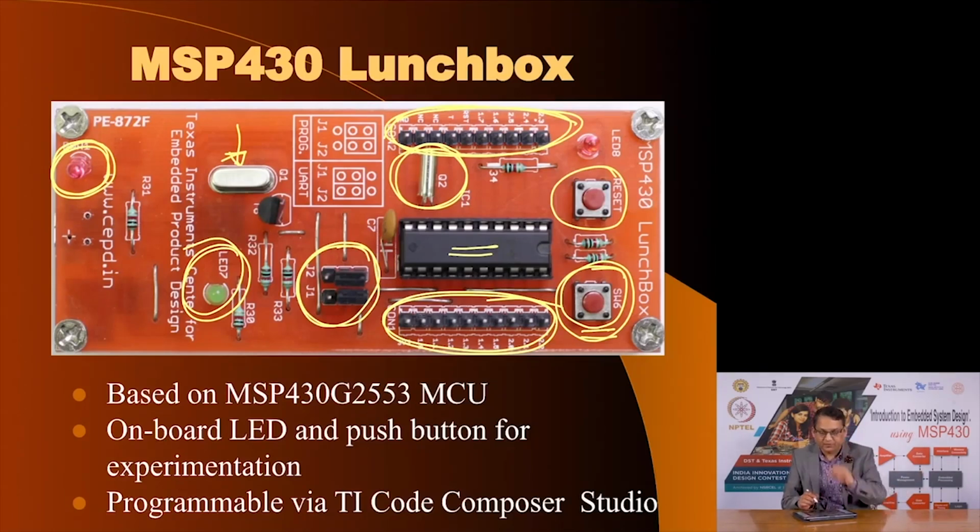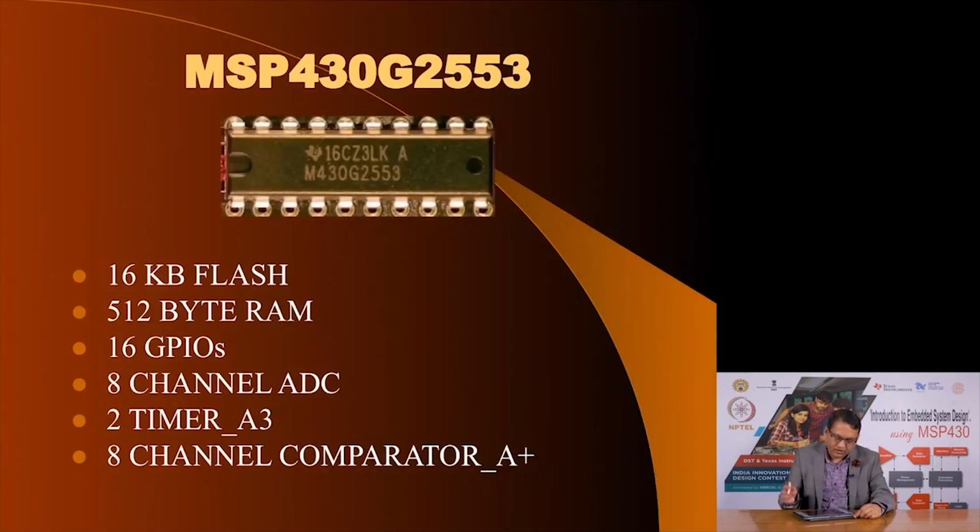These are shorting jumpers with which you can connect two neighboring pins. You have to engage them in certain way, and if you want to use the same USB interface for serial communication through your program during runtime, then you change the setting of these jumpers, and this is mentioned here and here. And this is a transistor which is required for some level inversion. This is the microcontroller that we are using. It has all these features which I have gone through before.